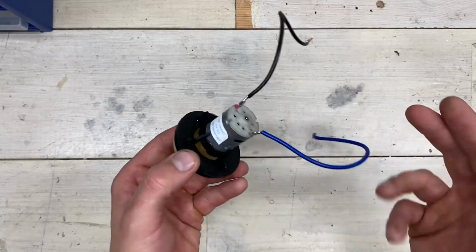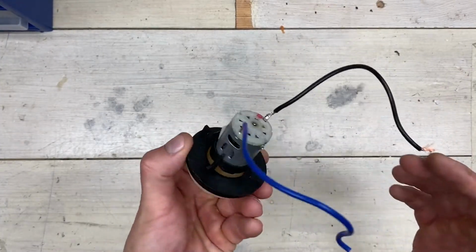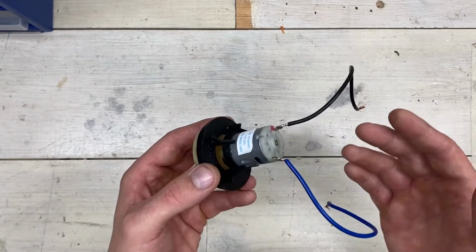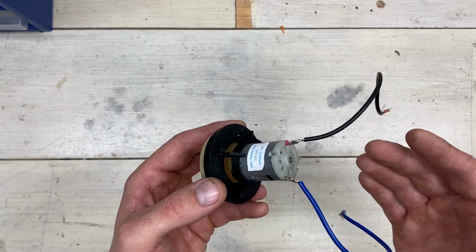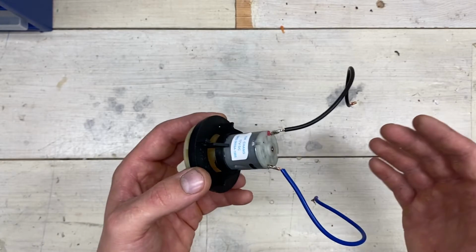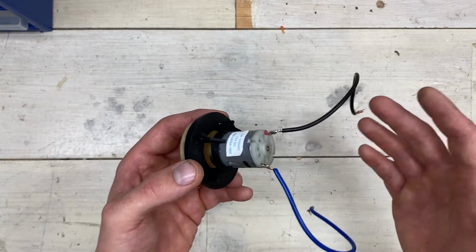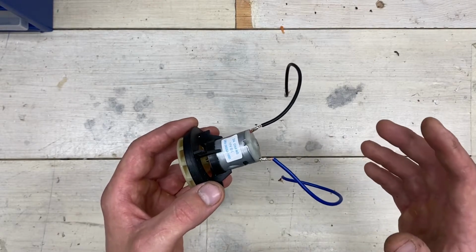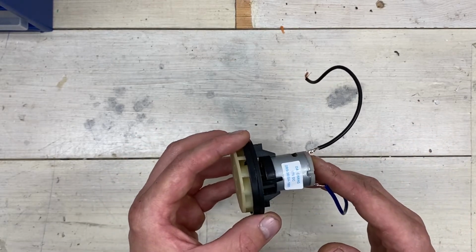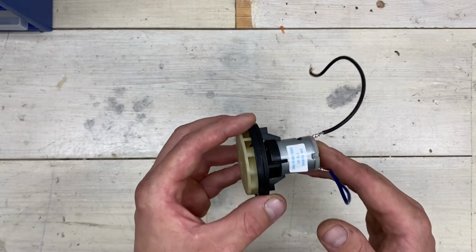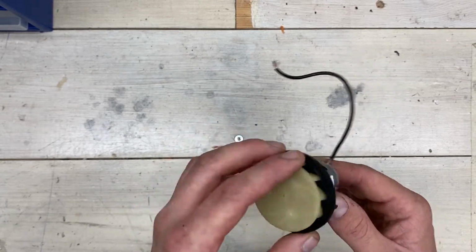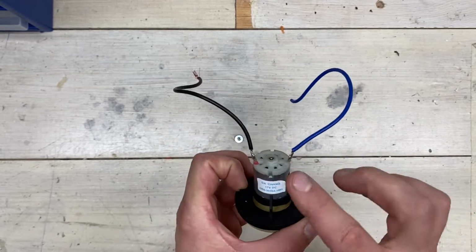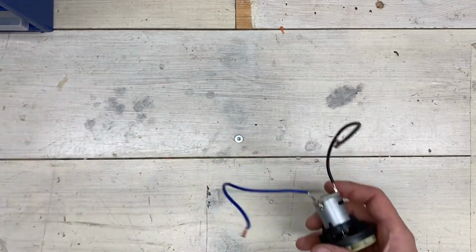Brushed DC motors come in all shapes and sizes. There are motors less than a tenth of the size of this one. And at the cold rolling mill where I work, we have motors up to the size of several hundred kilowatts, or several 100,000 watts of power. And within both paper mills and steel mills, it was for a long time really common to use DC motors because it is extremely easy to control the speed of them. The only thing you have to do to control the speed of a DC motor is vary the input voltage. Let me show you.